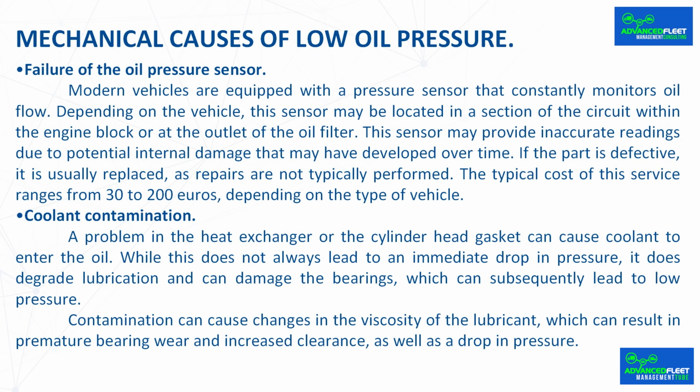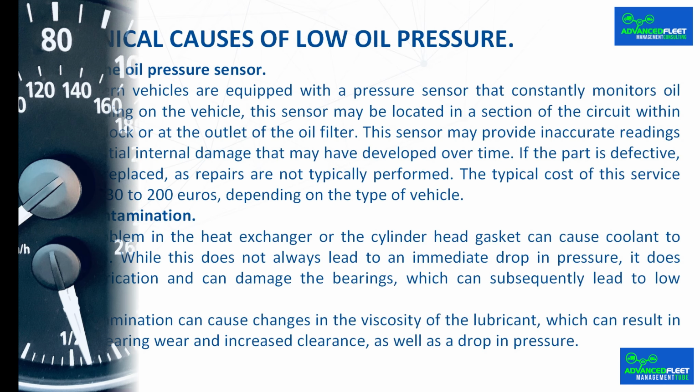Coolant contamination. A problem in the heat exchanger or the cylinder head gasket can cause coolant to enter the oil. While this does not always lead to an immediate drop in pressure, it does degrade lubrication and can damage the bearings, which can subsequently lead to low pressure. Contamination can cause changes in the viscosity of the lubricant, which can result in premature bearing wear and increased clearance, as well as a drop in pressure.